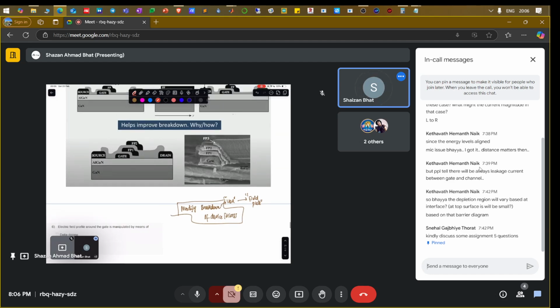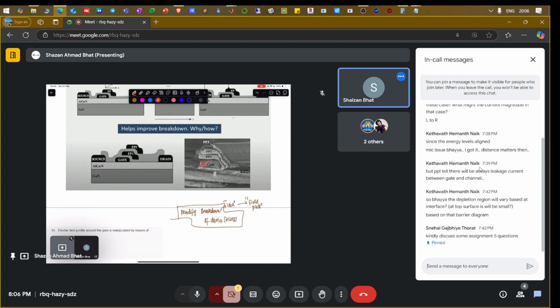If you see this figure, this is metal, this is again metal, this is again metal, and this is again metal. It's a weird system, but in between there is this dark thing. This is dielectric, and the dielectric should be throughout. These are separated, but this is dielectric. But on the back, all these gate plates: gate plate one, gate plate two, and this gate, are all shorted at the back.